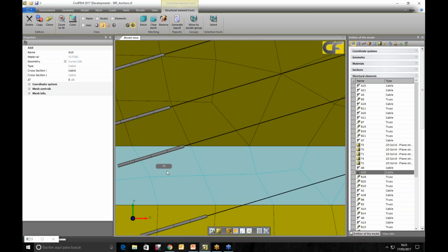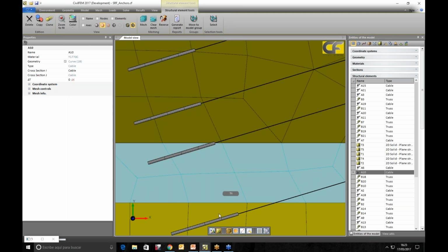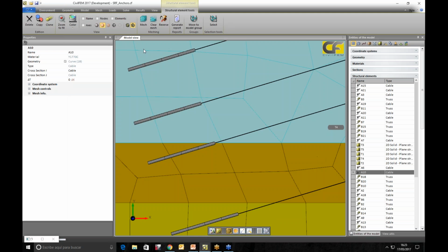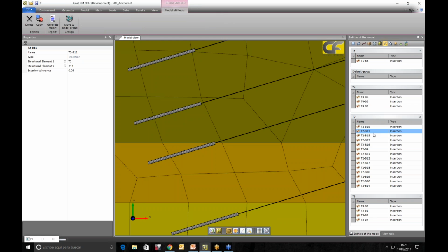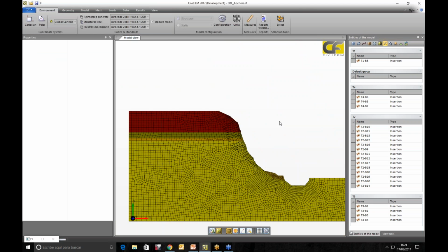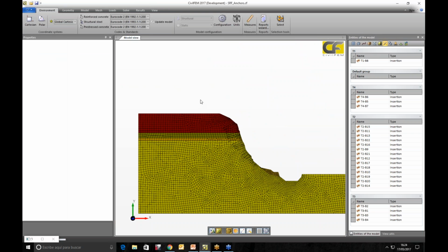Here you can see, if we zoom the elements, how we define the geometry, and once we mesh, we obtain our different structural elements, and here we can decide in the utilities which elements are to be inserted. We have solved it with the same loads: the horizontal acceleration, the load of the tower here, and also the pre-stressing loads on the cables. We have also started at 0.75 the safety factor, and solved increasing it by 0.01 until the model stopped. And we saw that the model stopped at about the same safety factor as the previous one.